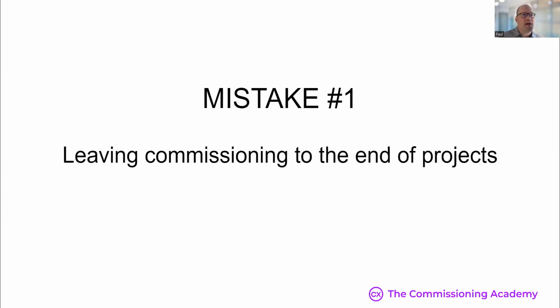They roll the dice at the end, and maybe you've had this experience on projects, but this is what leads to problems on projects. In fact, to be successful, the commissioning process starts right at the beginning during your FEED processes, and we need to be implementing our commissioning software during FEED to manage our commissioning processes through all stages of the project. When commissioning is left to the end, there's really no way to be proactive. All the problems are left at the end of the project, and there's absolutely no time to recover. The damage is done before on-site commissioning even begins.